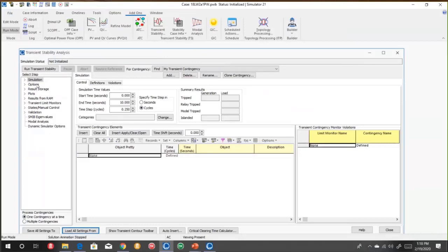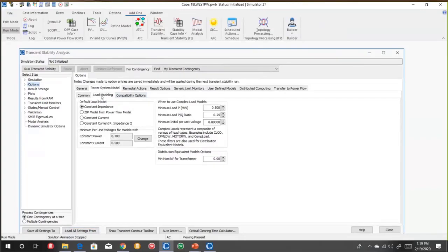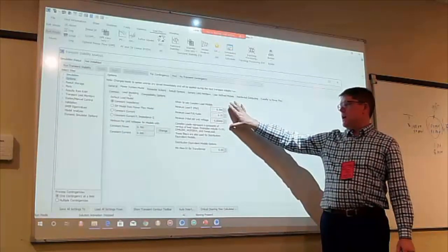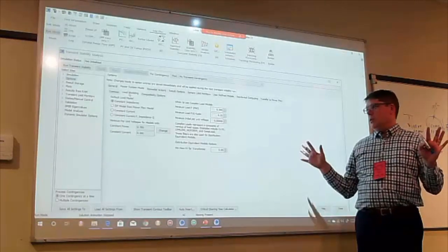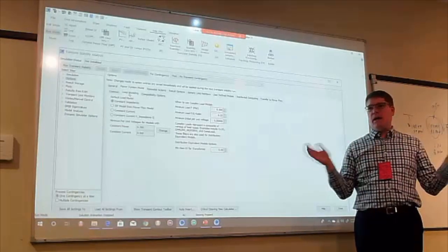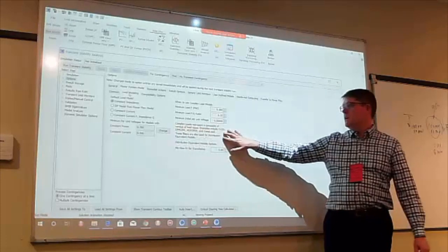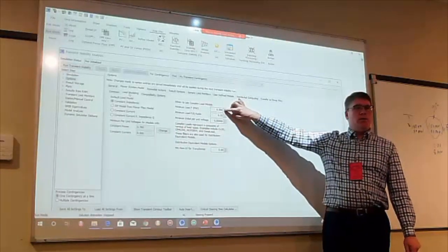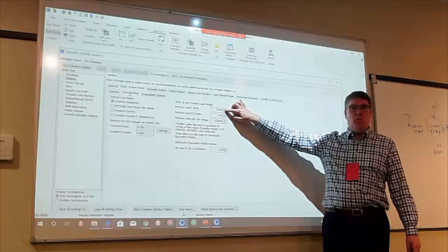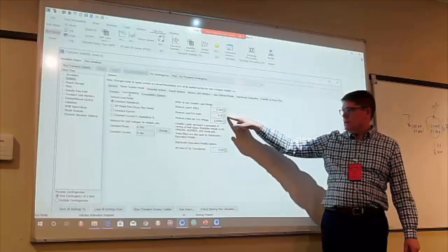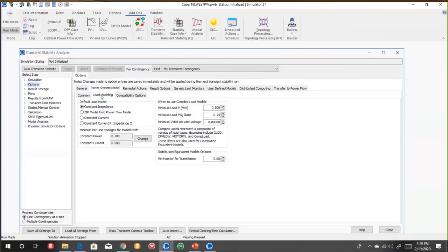So eventually we put in some options under transient stability, under option load modeling, that basically say do not use. In PowerWorld we implement it as any load that we consider complex, meaning it's meant to represent an aggregate of stuff. So CMPLDW, motor W, we have a comp load and a clod model. For all of these, if the load is less than some megawatt threshold, we'll never use a complicated load model, because what's the point? Or if the PQ ratio is less than 0.24, and you can edit this, that captures this case, as the PQ ratio here is 0.025 or something like that. Whatever, it's very small. So we can throw that out.